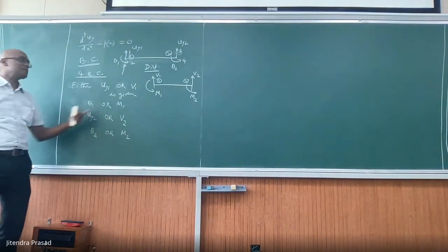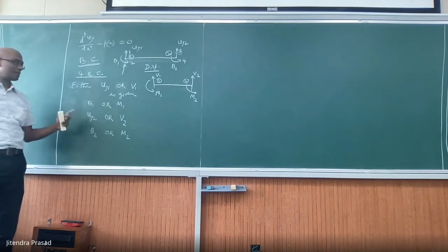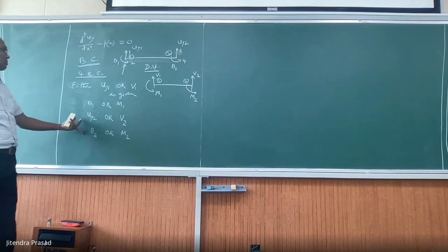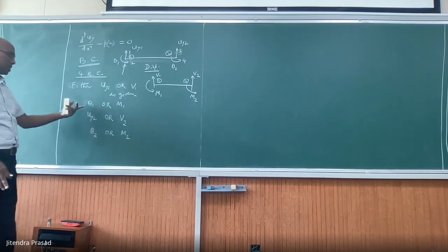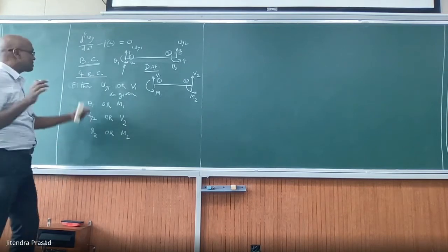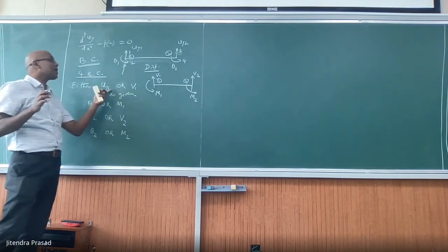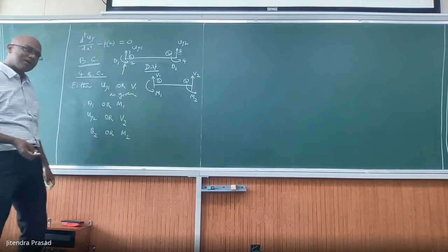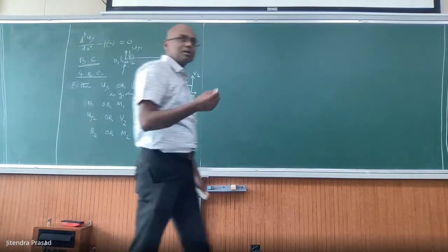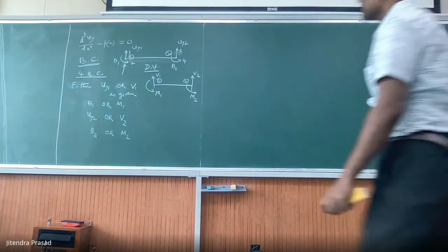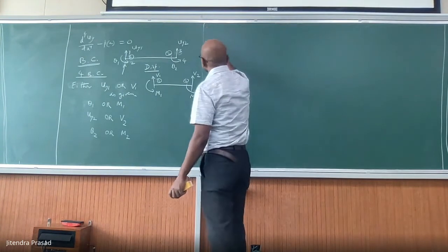You have one of these prescribed, but you cannot give both. It's not that you give uy1 and v1 as well. It's not possible, as we have seen earlier also. So either you give displacement or force, but not both. Remember that.